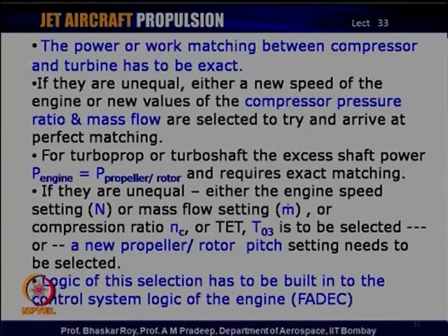And all the things that we have been talking about so far, that means selection of various component parameters, they all need to be built into the control system logic of the engine, which today is the standard FADEC control system, and that is how the engine is controlled. The various parameters of the engines are controlled, the fuel flow is controlled, the nozzle area is controlled, and if you have variable stagger compressor stators, they are also controlled using this logic, which is built into the control system of the engine.